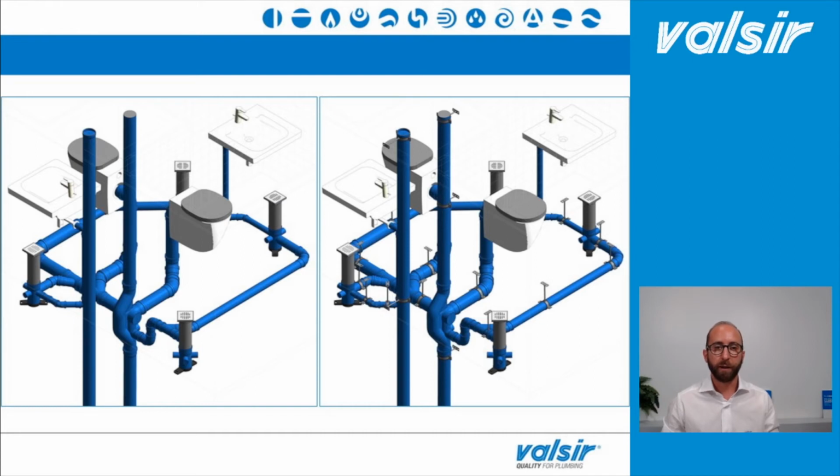If we are making an installation with all the pipes embedded in concrete, of course we wouldn't need a bracketing system. Just to give you a couple of pieces of information about this project, here the designers decide to use our ventilation branch fitting. This is a particular fitting that is widely used when we are speaking about a high-rise building, because it allows the designers to avoid using the parallel ventilation.